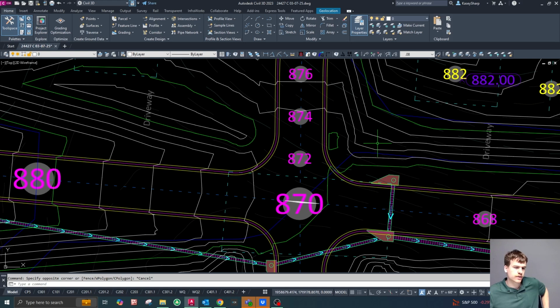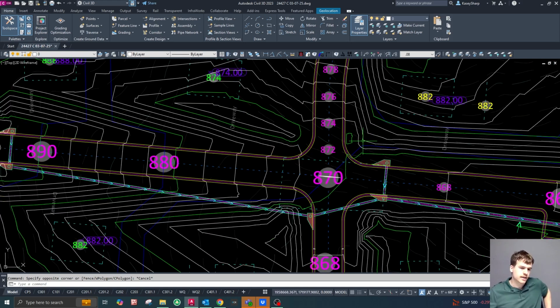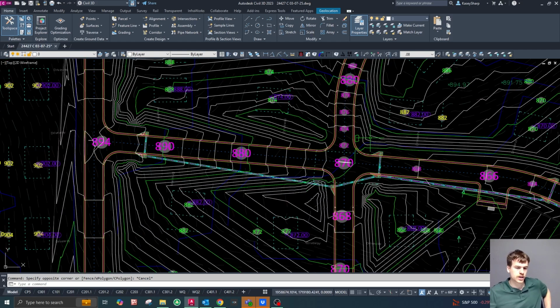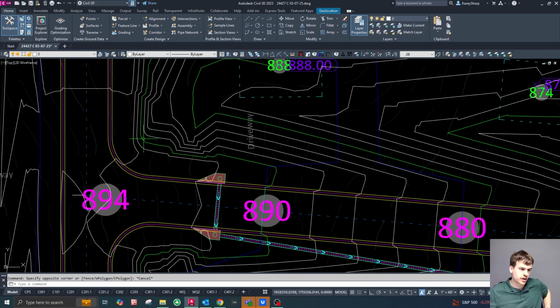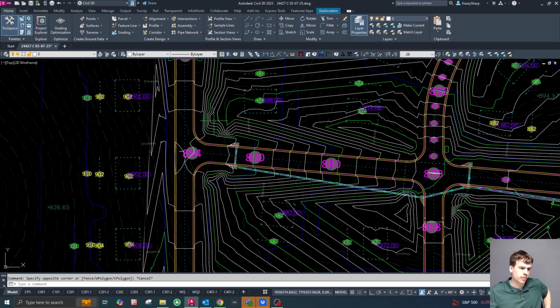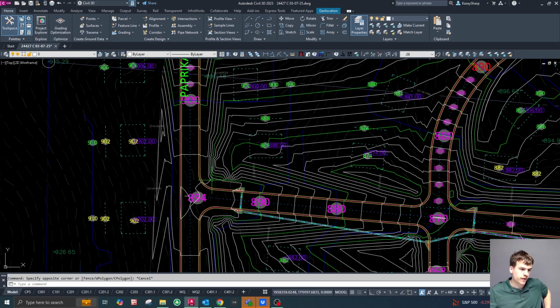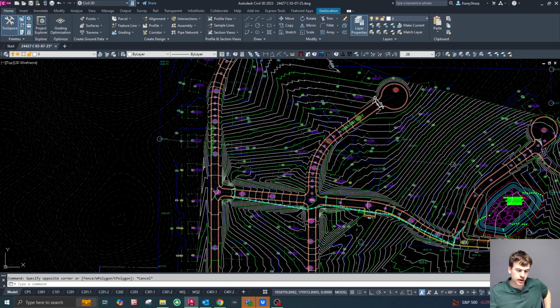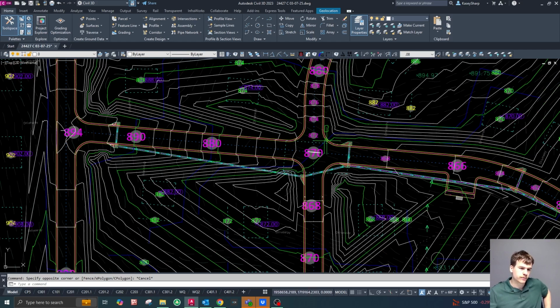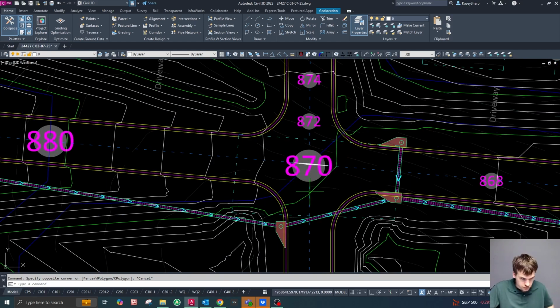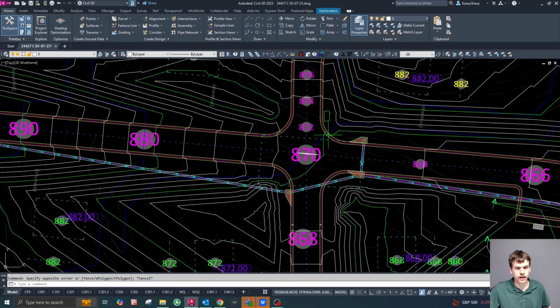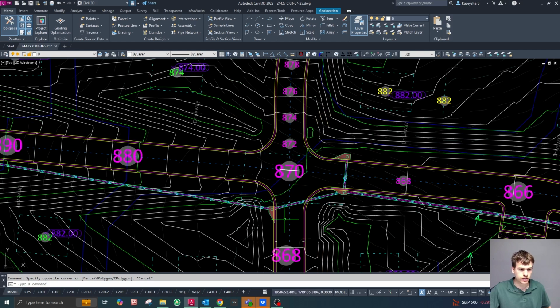And again, the surface is the final output that we want from our corridor. Thus, it's not necessary to edit the target mapping for those sections, which is why I didn't cover it in this video. And as you can see up here where there were bow ties, it still turned out pretty normal. You might do some fine grading to edit and change things later on, but that's just the next step following your corridor. The corridor does the vast majority of the work for you, as you can see. So now we have our intersection created, and it spit out a surface including this intersection,